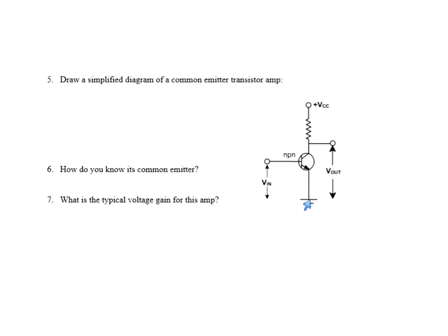But you have to be careful of that because sometimes you will have a resistor in there. It'll look like it's not attached to common. The key feature is to look for where's the input and where's the output. A common emitter always has the input on the base and the output off of the collector. Always. That makes it a common emitter.